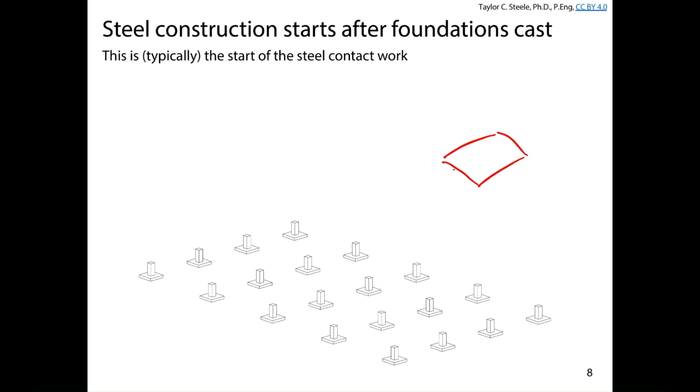And basically what the top of these foundations look like once they're backfilled, they'll have the rectangular pier that sits on the footing. And then within those, they're going to have these 4 things called anchor rods that are embedded into the concrete foundation with the reinforcement. Typically there are 4. There might be 6, but there's never fewer than 4 anchor rods poking out of the pier of the footing. And that's where the steel structure starts to be erected from.